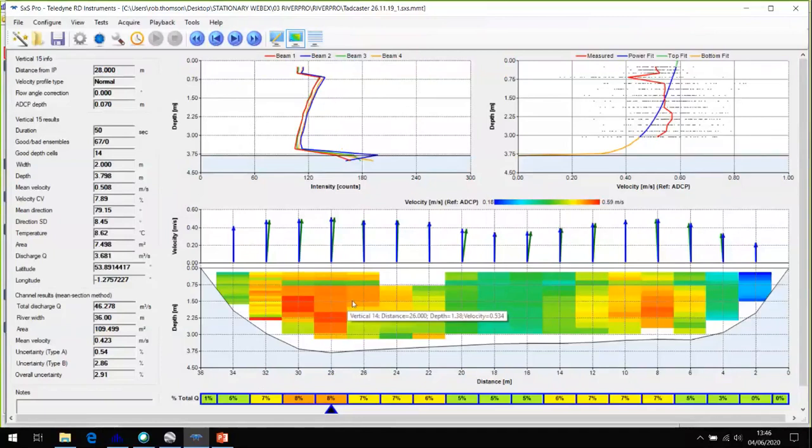But you're quite right. So for anybody on the call who doesn't have experience of the RiverPro ADCP, it's a good ADCP. If you got one, it would feel quite similar to your Rio Grande and your StreamPro. It has capabilities that kind of go across that pair of instruments. It's got automatic configuration like an M9. And it produces nice data for the most part, but it does have a tendency to produce weird data at the surface and also close to the surface. And in this example, in a moderately fast-flowing river, it's come up with this stripe, which is just erroneous.